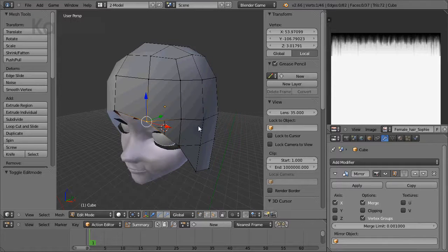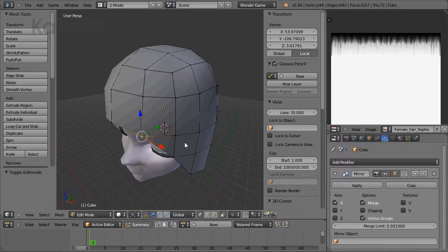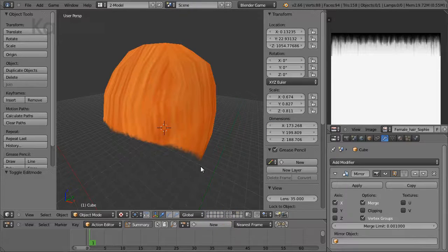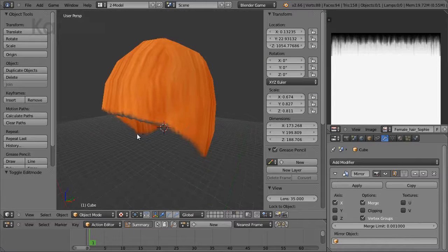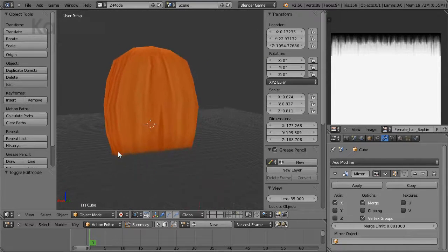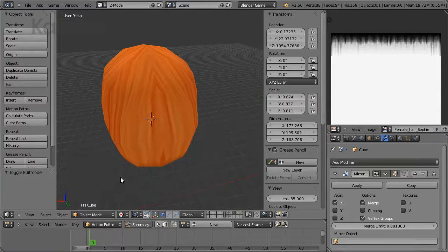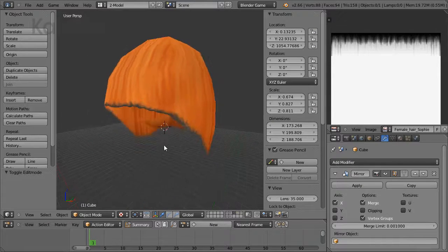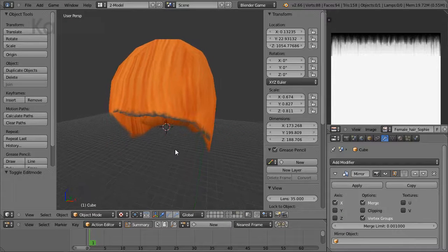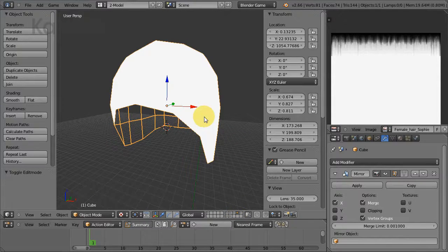But what makes hair tricky, which we'll see in a second, is that hair is generally linear. So you need to avoid unwrapping that goes against the grain as much as possible, or against the direction in which the hair naturally would fall. The general principle of unwrapping is to keep the direction in which the hair falls and reduce the number of crossovers or intersections or general misshaping that occurs as a result of overlapping or split UV maps.